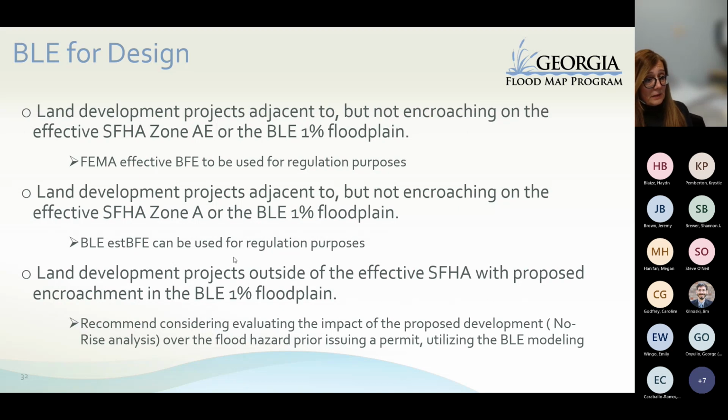So basically, evaluating the proposed development for no-rise analysis just to make sure that you're not going to make worse the existing flood hazard near the property. And for that, a developer or an engineer can use the available base level engineering modeling data.